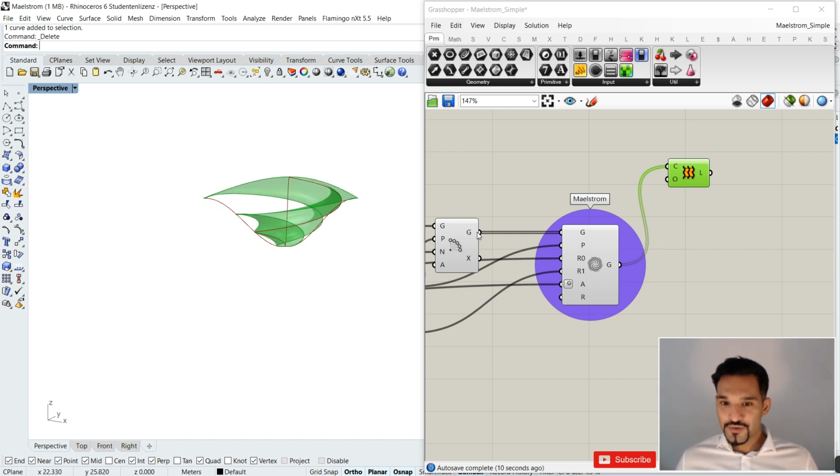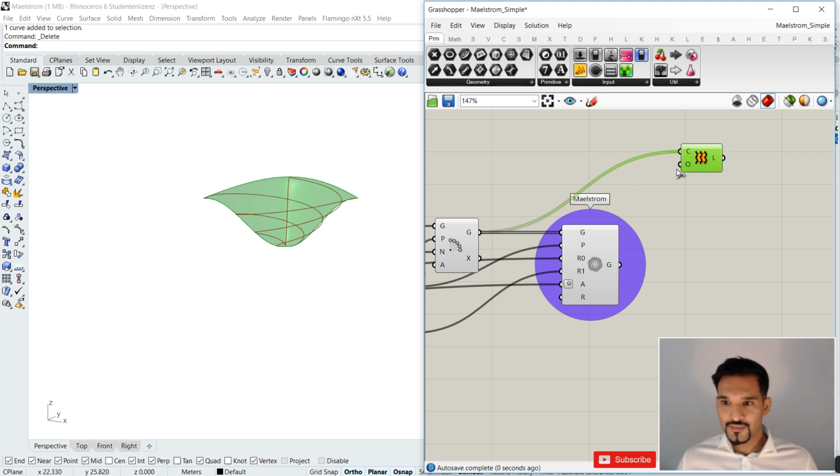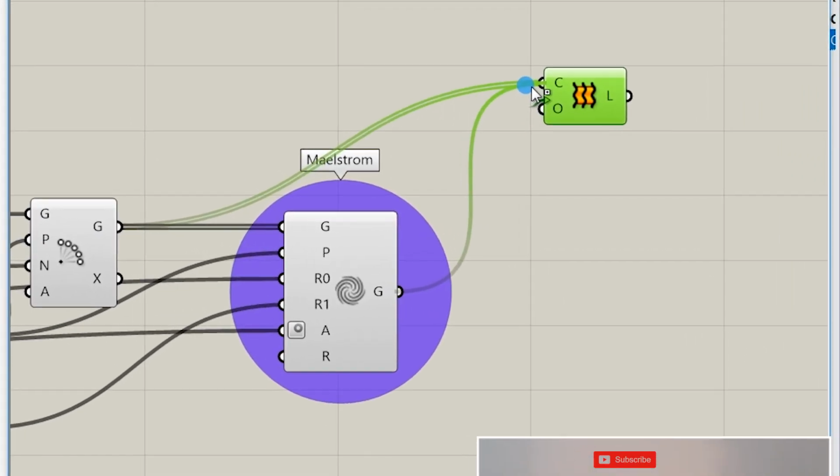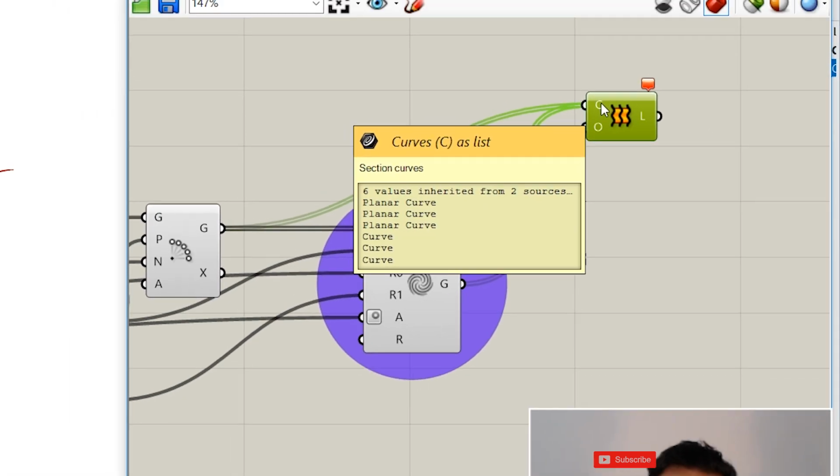But of course, if you now put in both values, so if I always just put 1, it will just replace my input in this component every time. What I have to do is actually press and hold my Shift button. You will see that I generate a little plus icon here. And if I put this in now, I have both of those inputs put into that list.